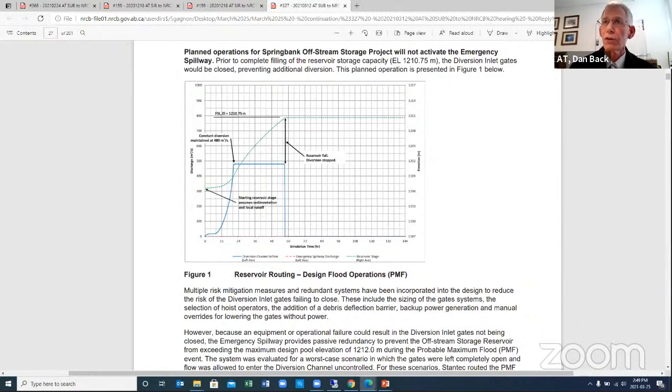We looked first at what's called a pseudostatic analysis, where we simply apply a horizontal load when we're doing the stability analysis. That horizontal load is derived from the likely motions that would occur in the design earthquake. That will give us some indication of the likely stability of the structure in an earthquake.